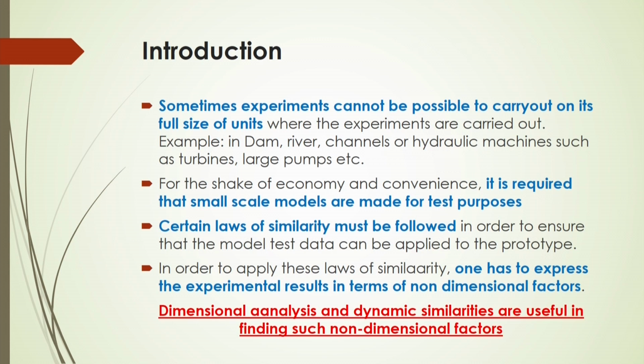For that, you have to work in such a way that it is economical and convenient, but it is required that small scale models be tested in such a way that they are useful for the same geometrical shape of the large scale system. In that case, you have to follow certain laws of similarity in order to ensure whether the model test data can be applied to the prototype or not.